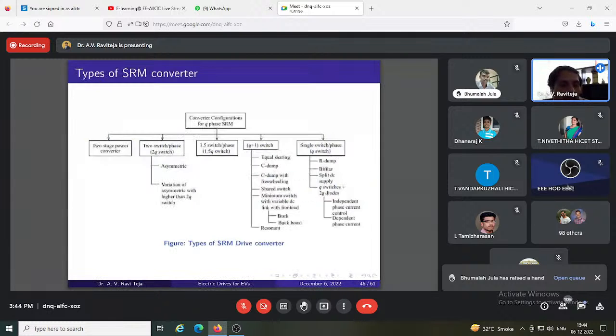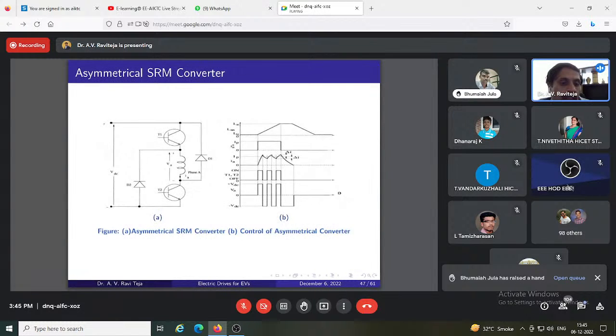So we worked on something, and in literature also there are many converters that are proposed for SRM drives. Fundamentally, they are trying to complicate too much, and also there is a limited demagnetizing or magnetizing voltage that can be obtained in the proposed converters. So you cannot apply any voltage as you desire in the available converters in literature.